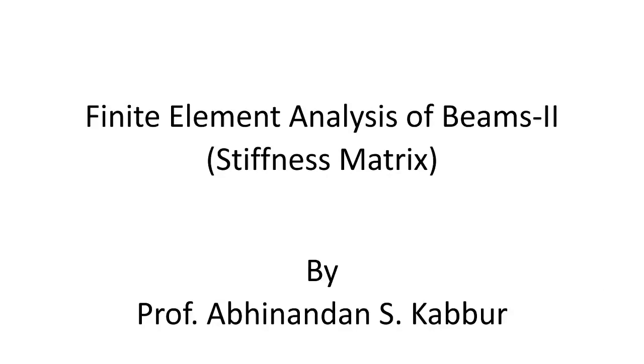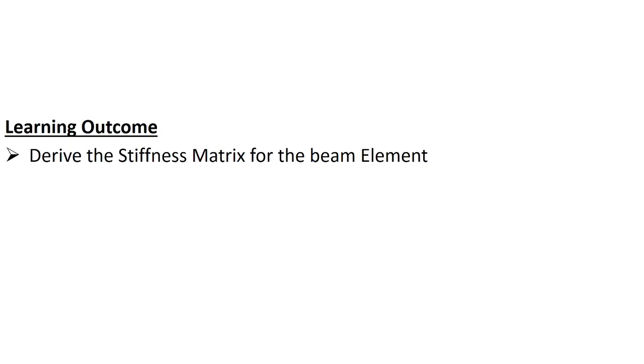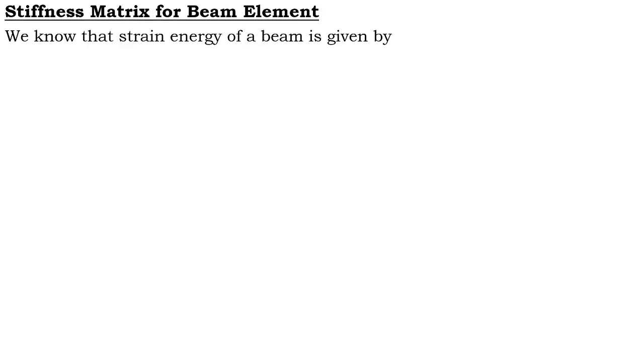In this session, we are deriving the stiffness matrix for the beam element. Now, the learning outcome for this session is to derive the stiffness matrix for the beam element. The stiffness matrix for the beam element is derived by considering the strain energy equation, and this is the strain energy equation we derived under the strain energy chapter in the mechanics of material.